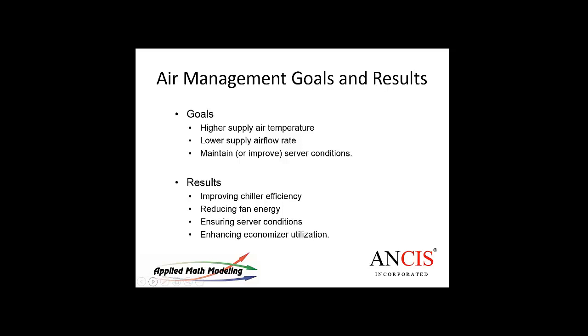So I guess the goals here are for higher supply air temperature and lower airflow rate to optimize the servers. In the case of the higher air supply temperature, that's an energy issue as well, right, Magnus? I mean, if we get higher supply air temperature, we're going to improve the efficiency of the cooling system. And if we reduce the flow rate, we get two benefits from that. Number one, we reduce the bypass airflow, and number two, we also reduce the requirement for fan speeds. I guess the third one is, by definition, it increases the return air temperature because if the air rate is slower, then it has more time for heat transfer and therefore higher return temp, right?